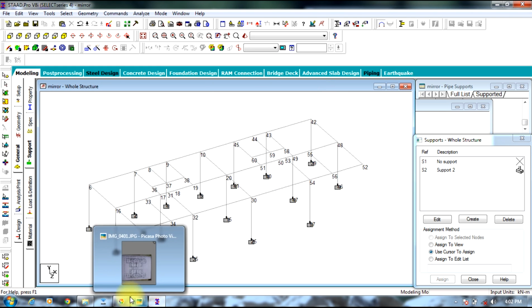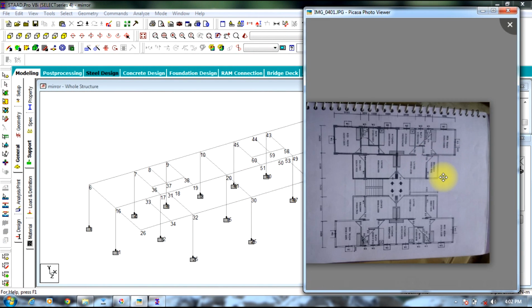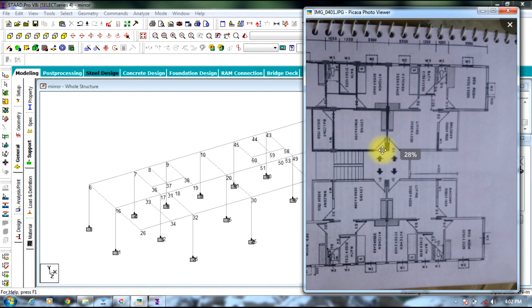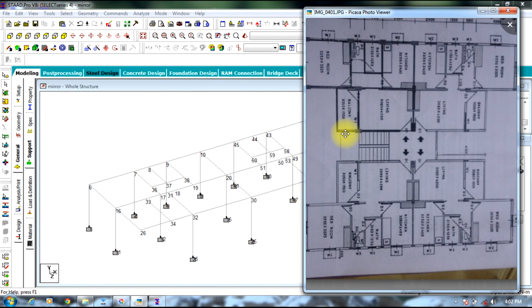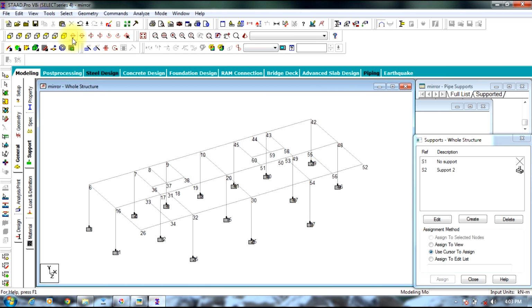Well, since we have finished one part, now coming to the other part, we need to mirror this entire structure on the other side. Before that, we need to draw a beam and a staircase beams. Only half of it will be required, since the other half will be mirrored. So go to 3D view.